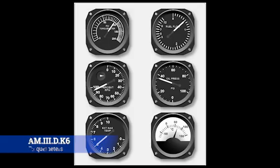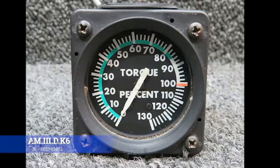Now, how it works is it measures the twist or strain in a rotating shaft using sensors, and then it converts the mechanical torque into a readable signal for display in the cockpit controls. Okay, so it's typically operated by engine oil pressure metered through a valve that's controlled by a helical ring gear that moves in response to applied torque.